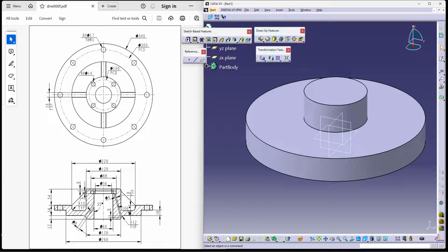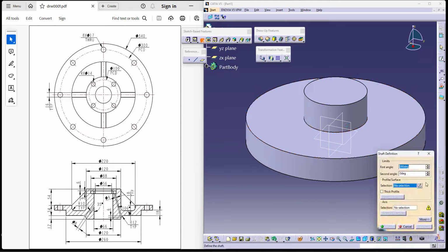As you can see in the drawing, this seems to be like a support, like a stiffener. But actually there is no material here. If there were any material here, you would be able to see hatching. There is no material here, but there is material throughout the other area. Since there is no hatching, there is a slant cut inside a cylindrical shape. The shape actually looks like this. Let me try to make it for you.